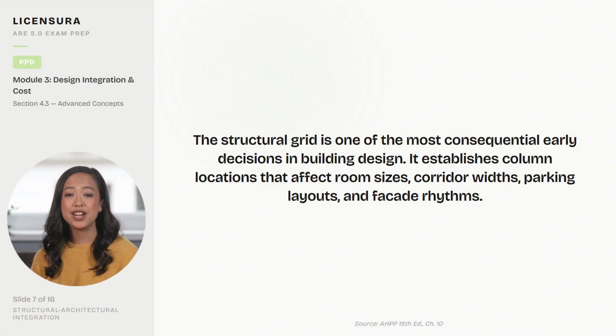The structural grid is one of the most consequential early decisions in building design. It establishes column locations that affect room sizes, corridor widths, parking layouts, and facade rhythms. Grid coordination between structural and architectural requirements must be resolved in DD.